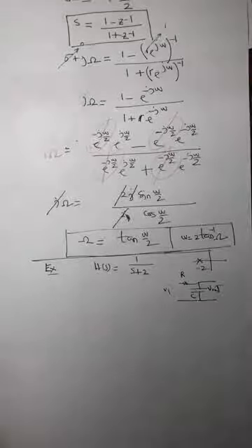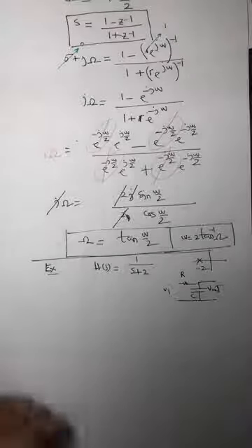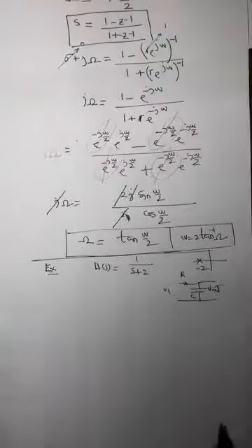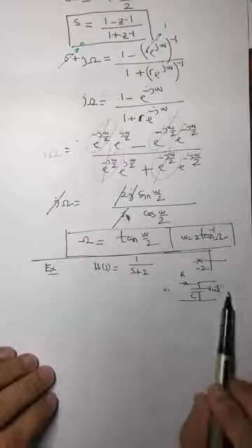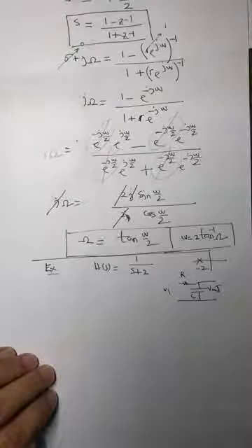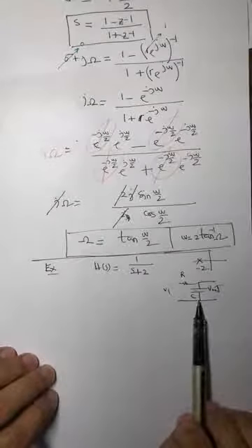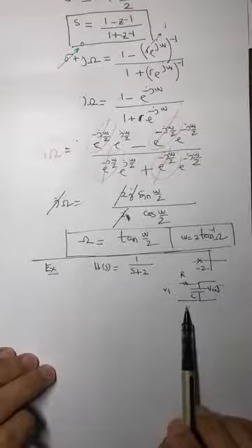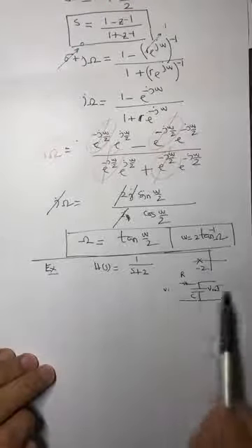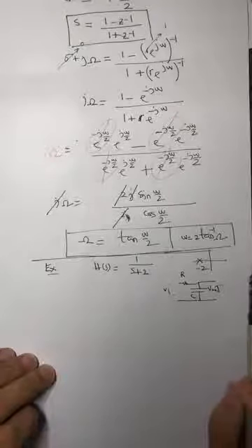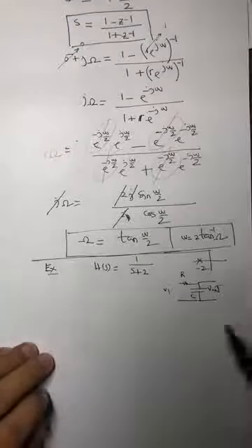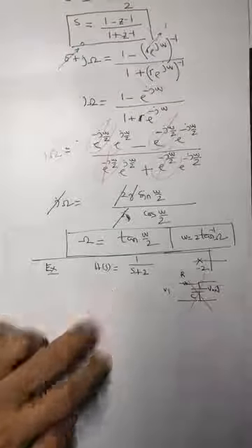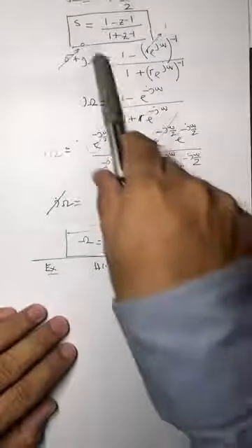And now you can convert it into a computer program. Instead of actually putting these things on the breadboard, feeding in Vi and then getting Vout, you say, why shouldn't I convert it into a simple first order difference equation and write a program? Obviously, I need to digitize the input and convert the output back to analog, which I don't mind, but I can throw away the circuit. Let me write a computer program by using this transformation.